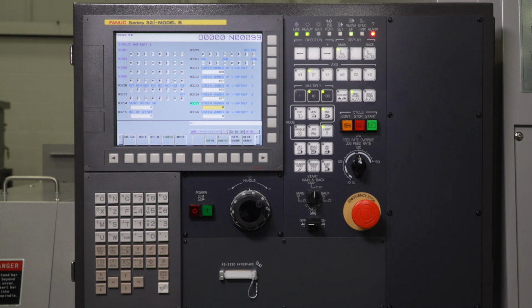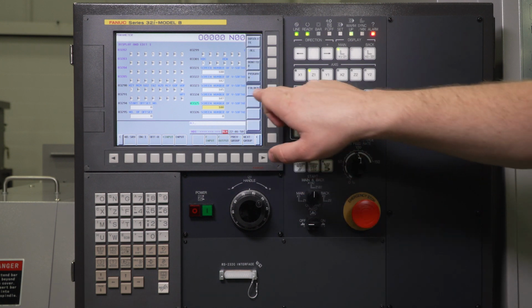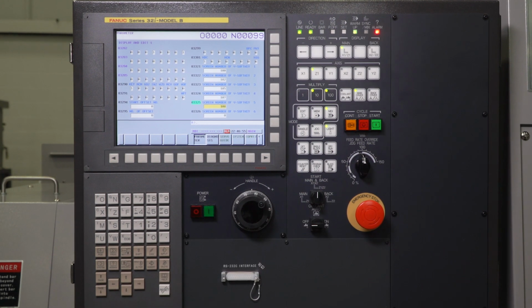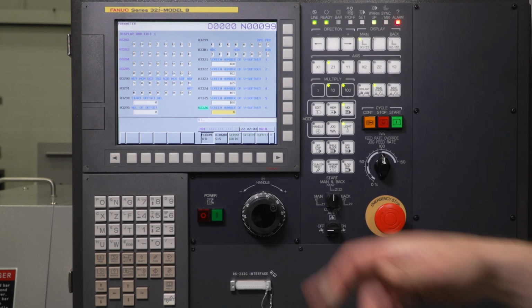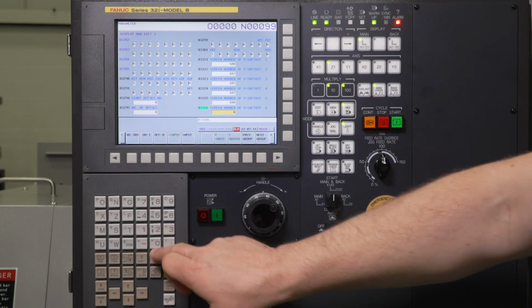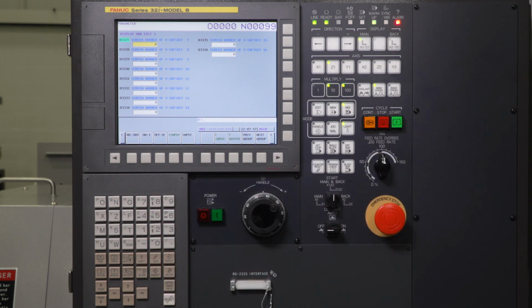Let's go back down. 3325. This is going to be the folder screen, which is going to show all your programs that are resident in the CNC control. So we're going to do 108, input, and that's going to give us folder. So that's going to show us our folder screen. Let's go back to our parameters. 3326, let's make that program check. That's going to show us, when we're running our program, what codes are modal and what our current feed rate is, current spindle speed, and things of that nature. So let's make that a 110 for program check. We're going to just continue on to 3327.